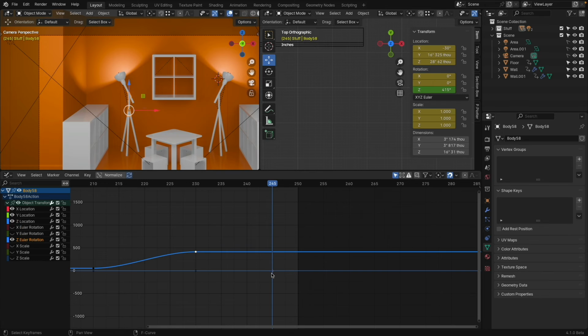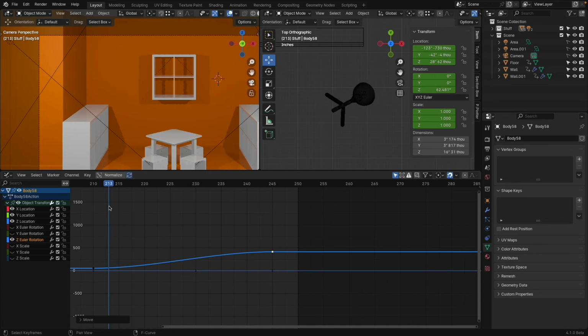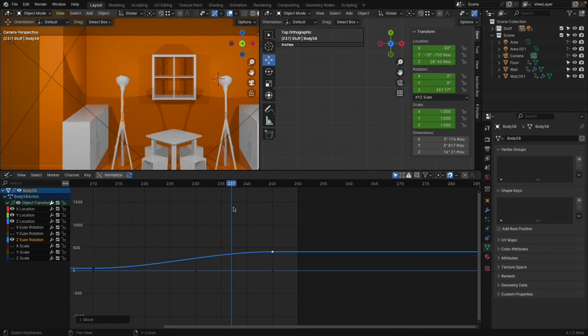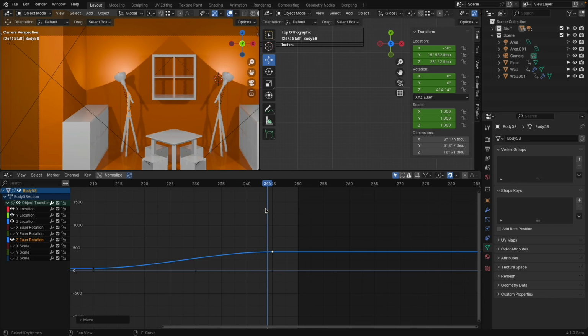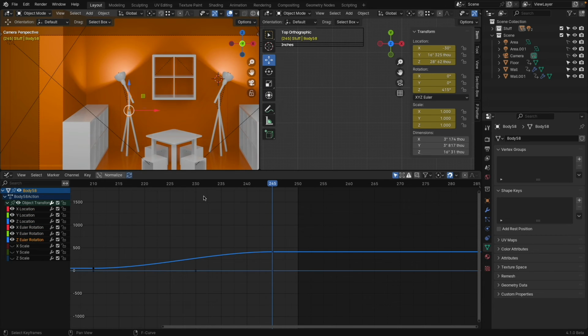So here's the position for the location, but I did my rotation here. So no problem, G and X, bring this over. Now you see over the span between two keyframes, they're nicely choreographed and dancing. A, A, B, select all this stuff, delete keyframe. Oh, no, this one we need. That was for the movement. Careful with what you delete. Pro tip, trust me.